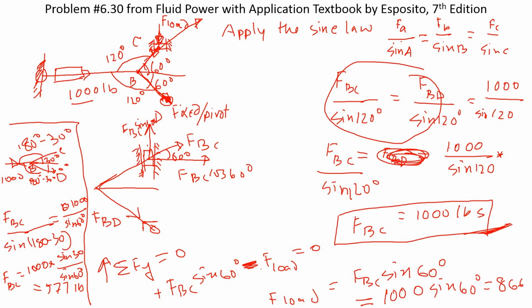When you have to find the forces, the sine law will be easier than resolving the forces. Resolving forces helps when you have to take the moment later on. If you're not taking the moment, apply the sine law to find forces instead of resolving forces.